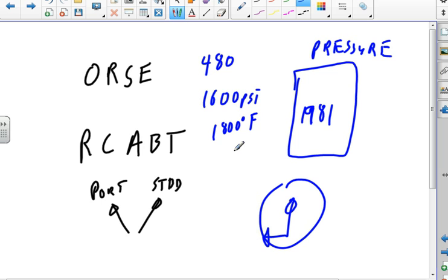I'm the engineer, and I'm out of the bunk, and we're consulting the reactor plant manuals. And we get to the place where, okay, you have to go solid. Running the plant solid. So now we're going to pressurize. We're going to add water to the plant, collapse the bubble in the pressurizer. So now the plant is solid, and at 1,600 pounds, we're safe, right?